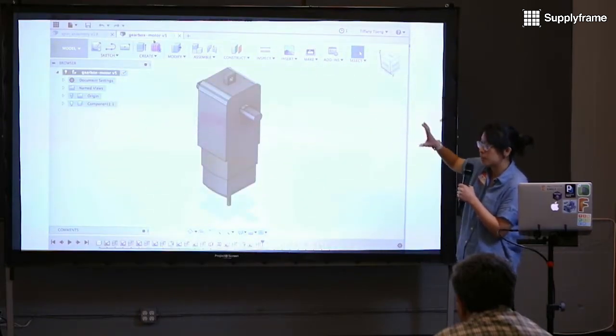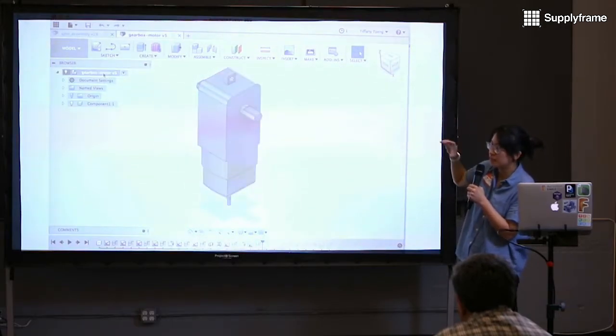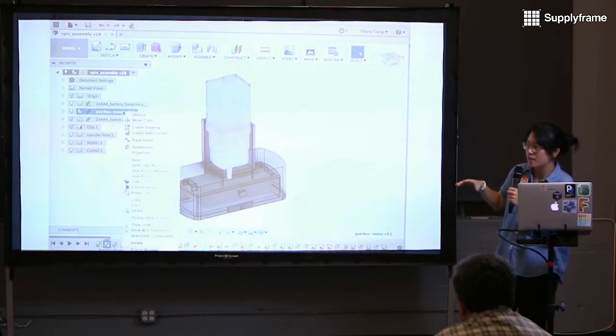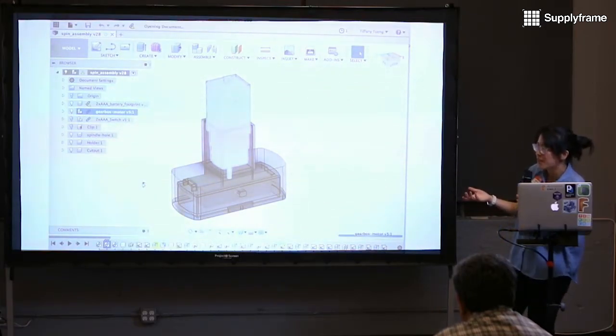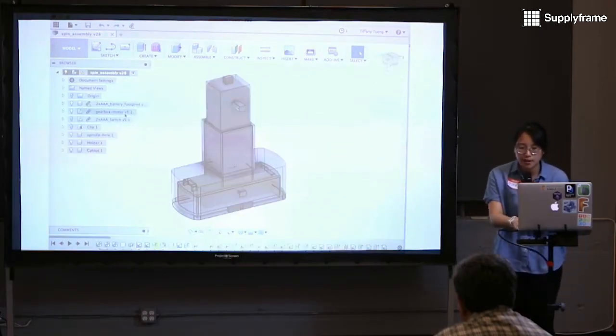If I want to edit it, I actually have to open it in a completely different workspace. This is really a technical limitation, that XREFs can't be edited in place, and that takes away a lot of the functionality that we're trying to encourage, where you work back and forth. But in the case where you're working with a fixed PCB, it doesn't really matter. With the XREF, you could insert it into multiple designs. So there are trade-offs, pros and cons to these two approaches.